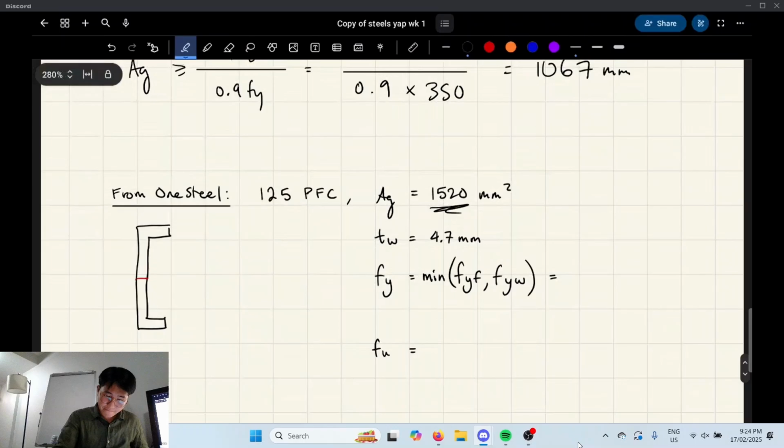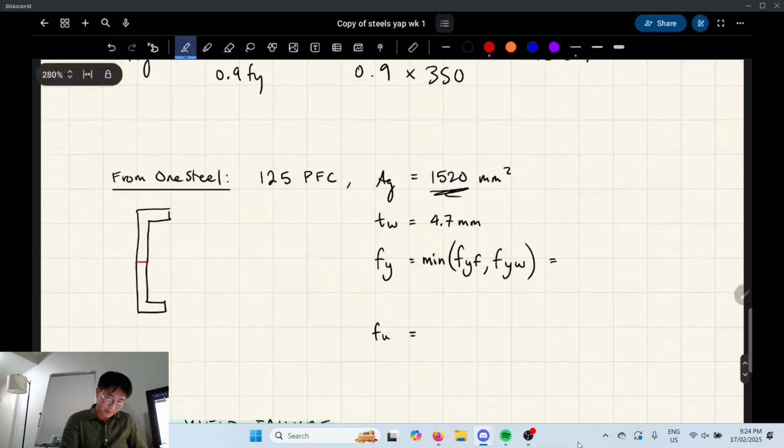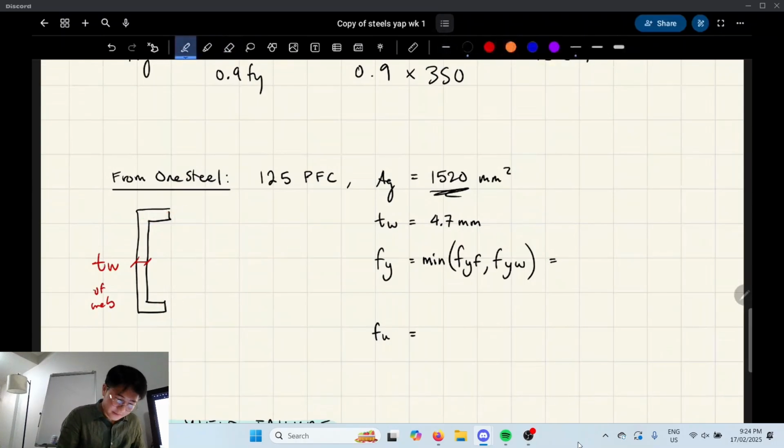They're like the standard sizes of beams, but not just beams, any member. It's like Legos, predetermined sizes for whatever. So a PFC looks like this, as we mentioned. What part is this on a PFC? The center. There's a word for it. Web, exactly. So tw means the thickness of the web. And these are the flanges here for a PFC. This is kind of indicating the size.